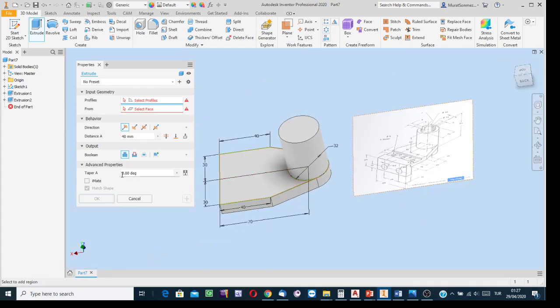But here, applying the extrusion process, I will indicate this profile one more time in the opposite direction. Yes, flip. From the profile, it is over the top side surface of the base, to the tip of the lower cylindrical extension. Distance is equal to 10, the thickness of this part. Length of the extension at the bottom side is 10.